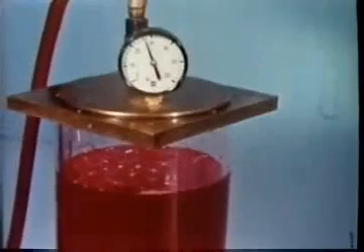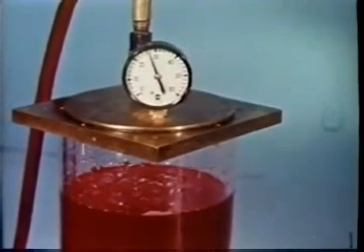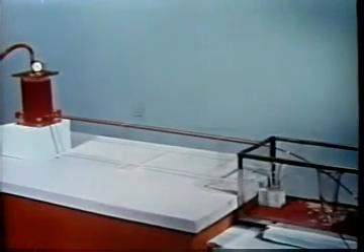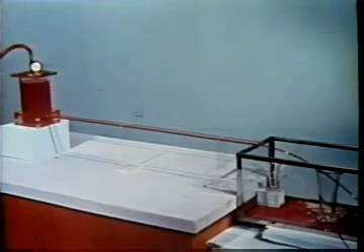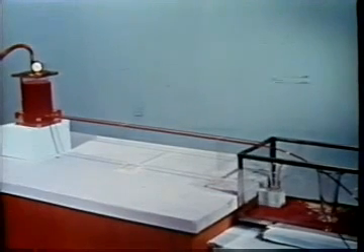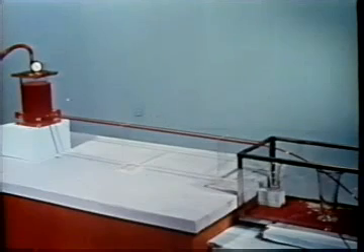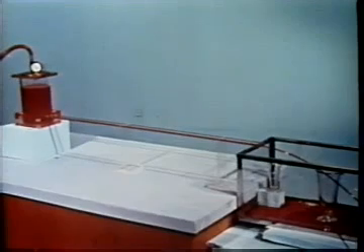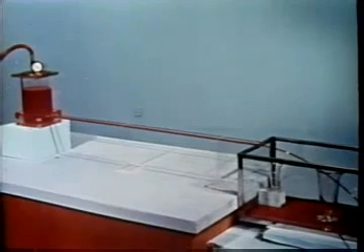Here the tangential stress due to viscosity is balanced only by the driving pressure. Though the Reynolds number is not necessarily small, there is no change in the inertia of the flow as it passes through the tube, so that the results of calculations of the kind used in thinking about low-Reynolds number flow are applicable.